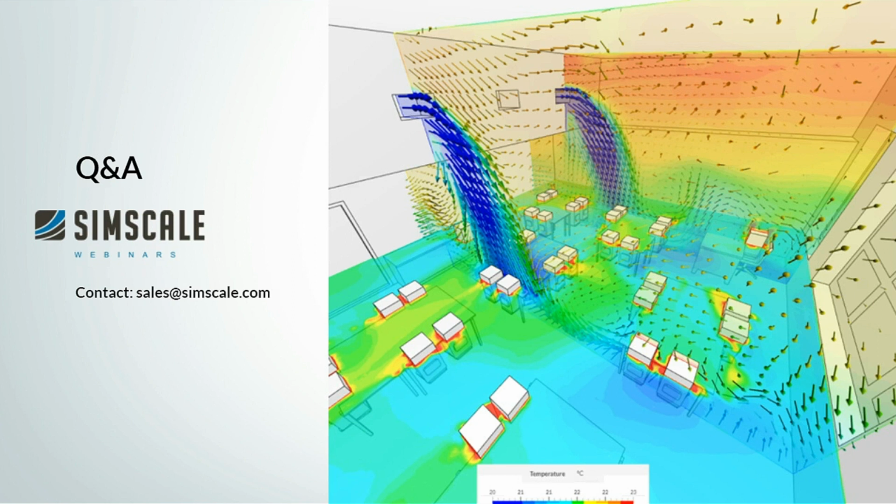We have a solar load functionality where you can input the coordinates of the building, the north direction, and the time and date. This will then be used to put the solar rays in the right direction. And we have the ability to put semi-transparent windows with specific emissivity and transparency. Then the solar radiation is taken into account in the heat gain inside the building.